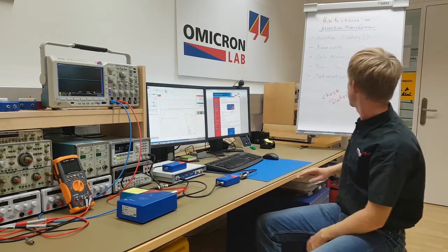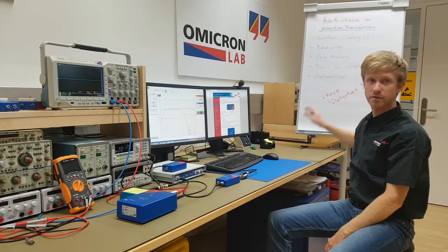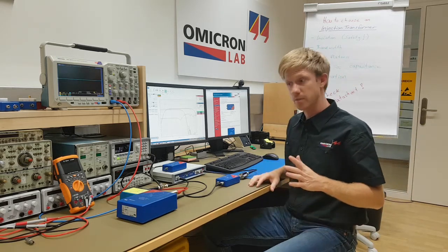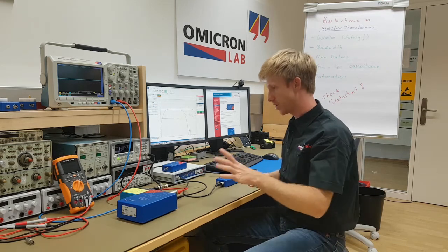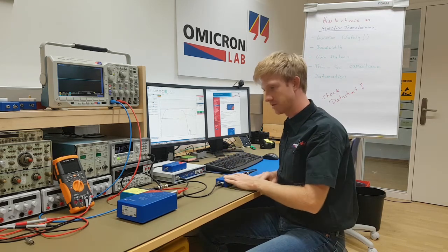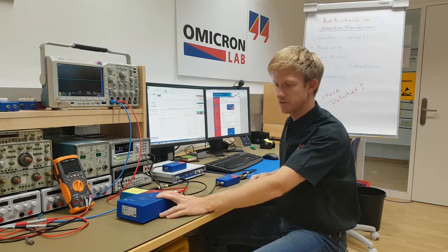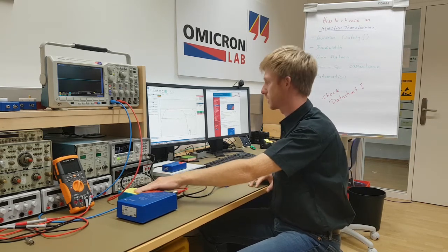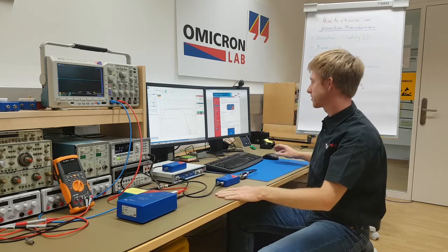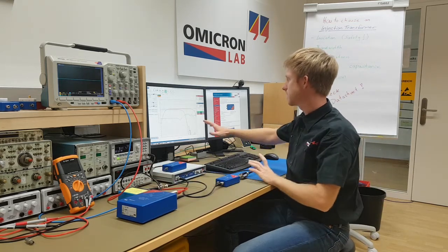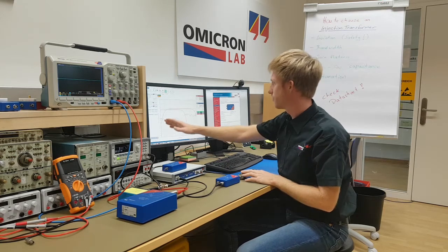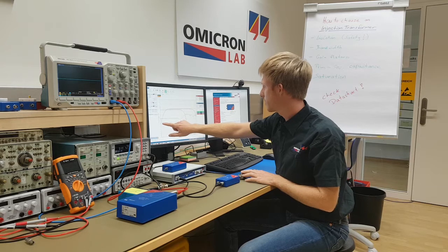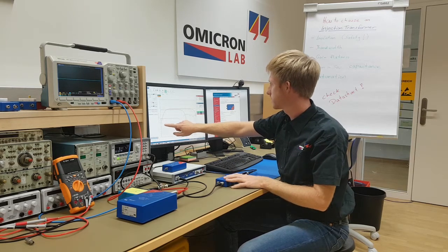The next thing that we have on our list is bandwidth and gain flatness, and that's somehow related. I have performed gain measurements on all the three products I have here: our B-WIT 100 injection transformer, our B-LFT 100 low frequency injection transformer, and a product that I call product R. Let's have a look at our screen, and on the screen I have all the three curves between 1 Hz and 10 MHz. Here we see the red curve, that's our B-WIT 100 injection transformer.